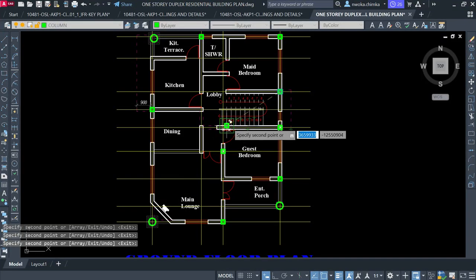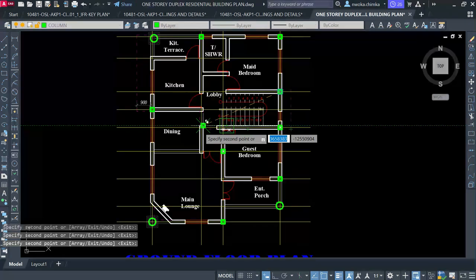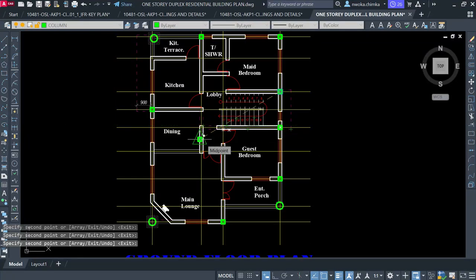Okay. So what I was saying is that the way you put your column points or do your GA, when I say GA, I simply mean column points and then framing, how your beams are running and then slab. So the way you do your column points for pad foundation is different from the way you do your column points for a raft foundation, and also different for a pile foundation, right?